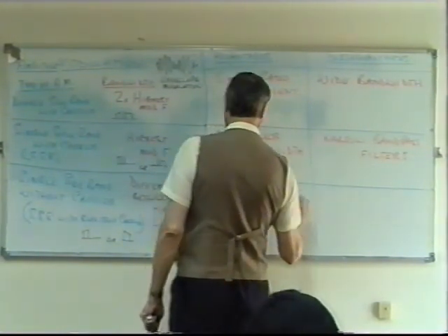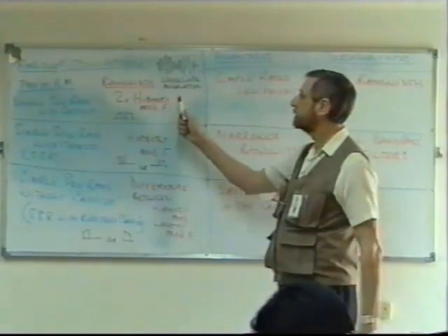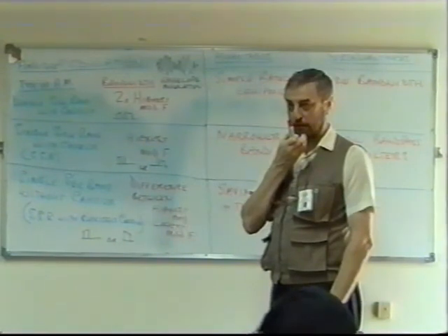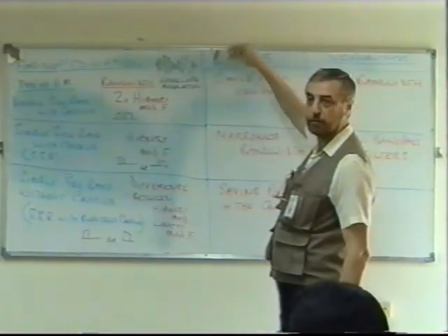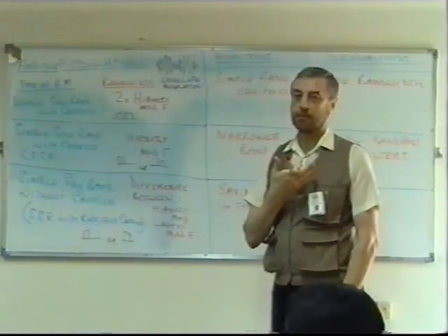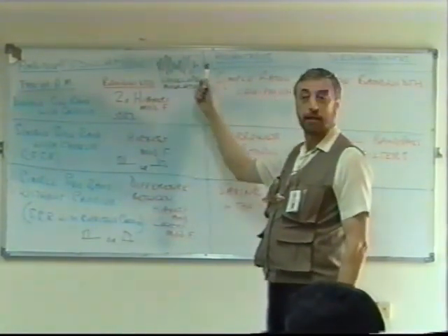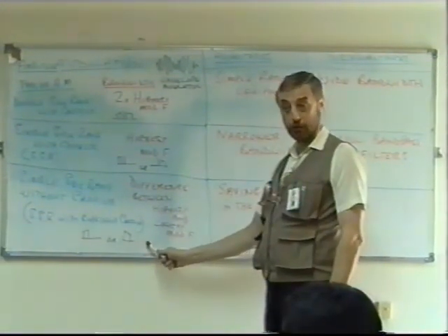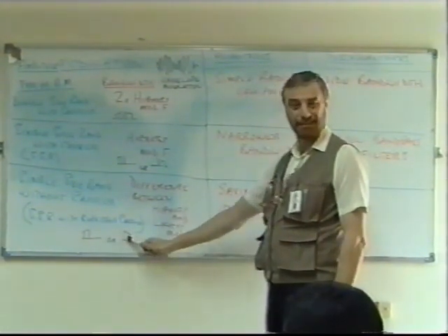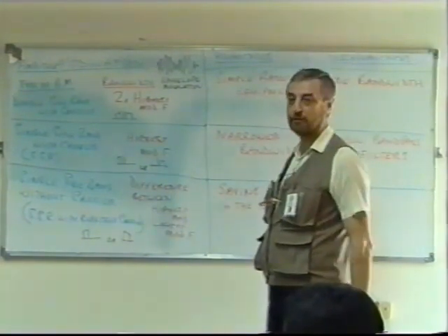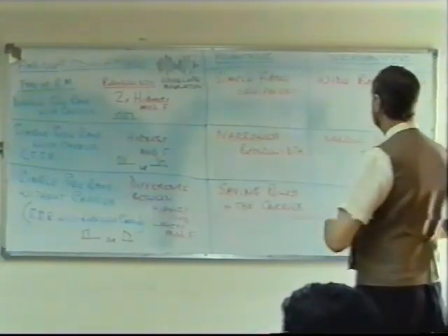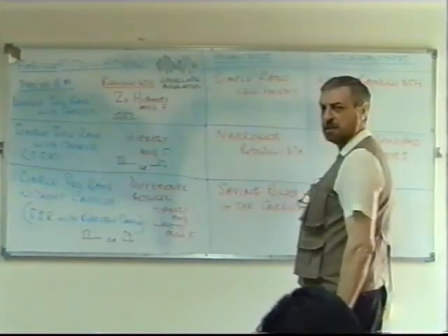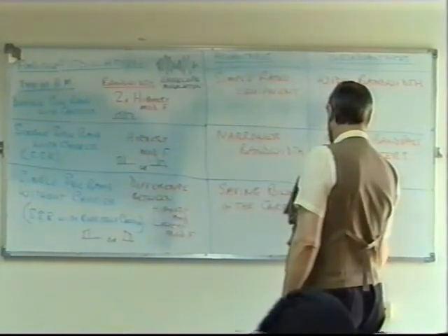Very efficient. Because what happens with this, take this signal here, if you are speaking into the microphone, then you're modulating your carrier, aren't you? What if you stop speaking? The carrier continues to be transmitted. Yes. But here, if you stop speaking, this disappears. Nothing's transmitted. Nothing. It's quite efficient in that sense. But again, the disadvantage is we need special receivers. Yeah, very special receivers.